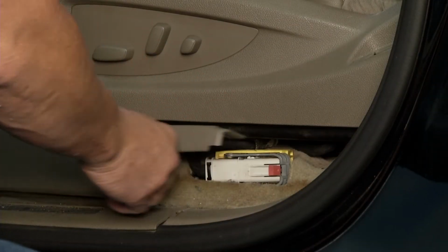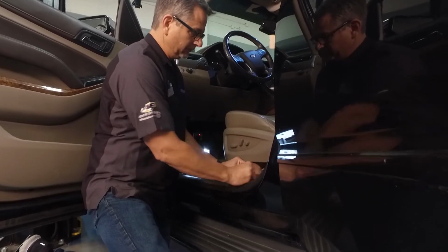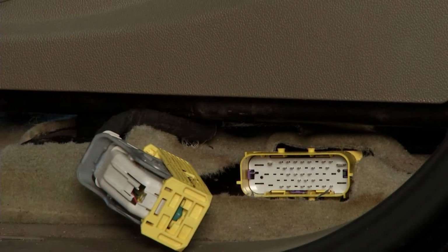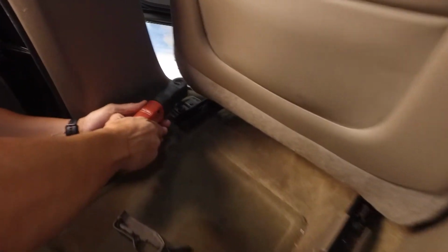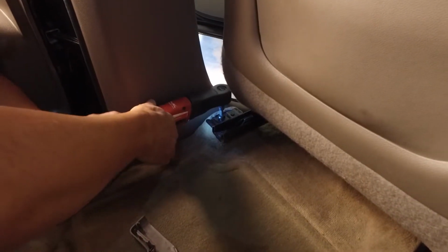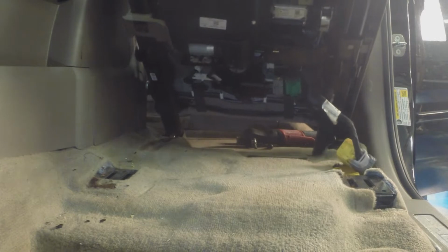Seat was super simple to get up. I just took the trim panel off the side, popped it off. Once it was off, I could gain access to the little plug there. I unplugged that, which went to the actual ABS components. Got it kind of loose on the front end here. Then I went around to the back. I had some Torx bolts back there, took both those Torx bolts out. Once they were out, that allowed me to lift the seat up, get it out of the front track, and tip it up. And that's where we stand right now.